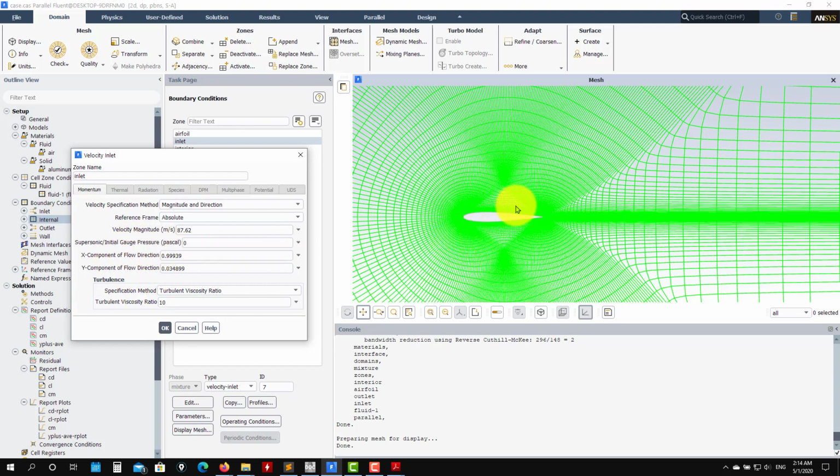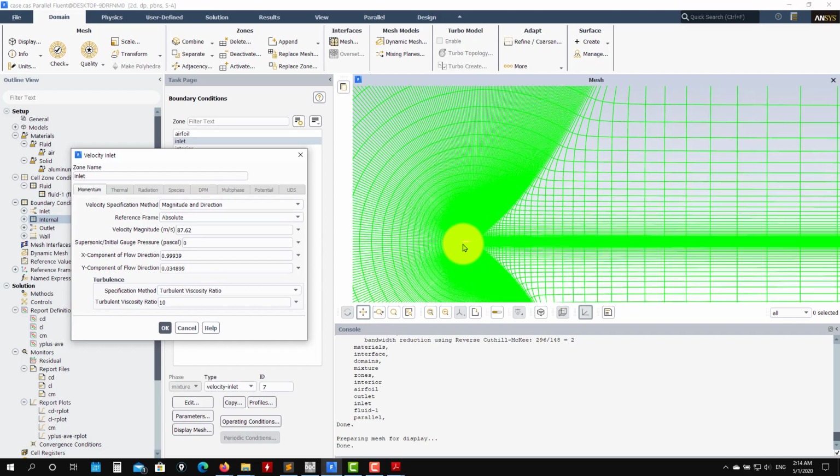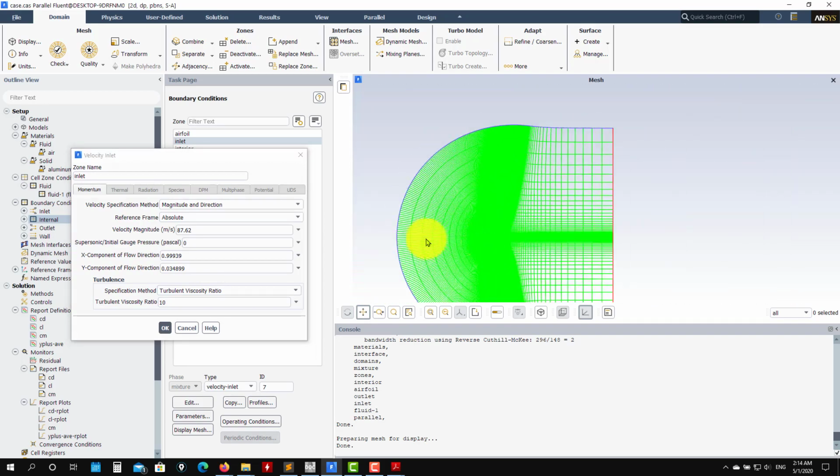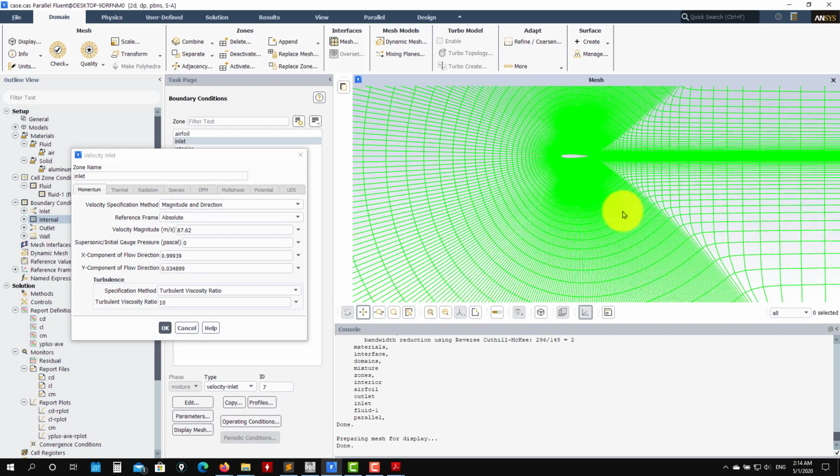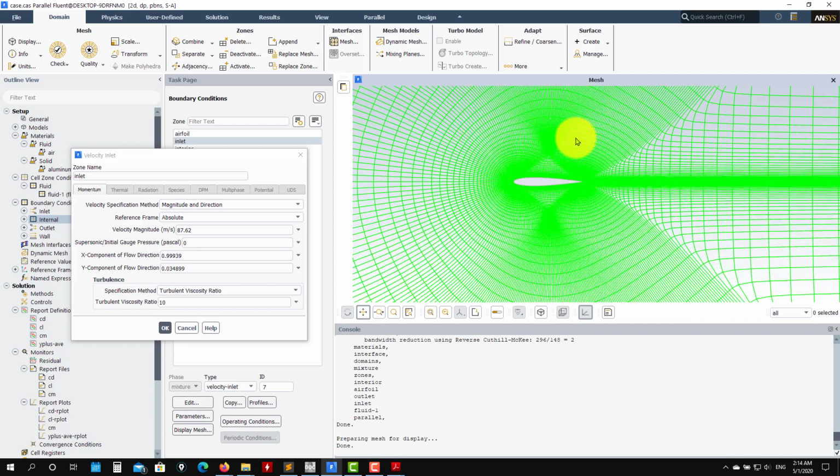Alternatively, you can rotate the flow, and this will always be 1, 0. But if your incoming flow has an angle, you will also need to give this rotation matrix when you compute the lift and drag, which we're going to do. Just to make it clear here, let me draw on screen.